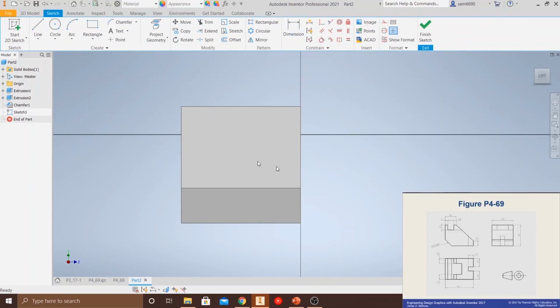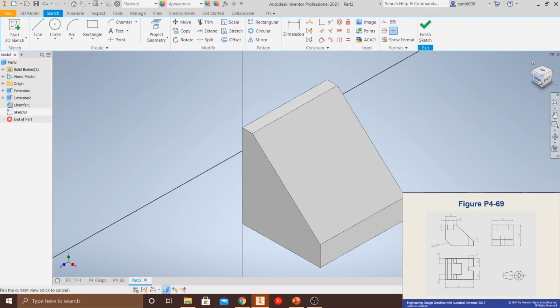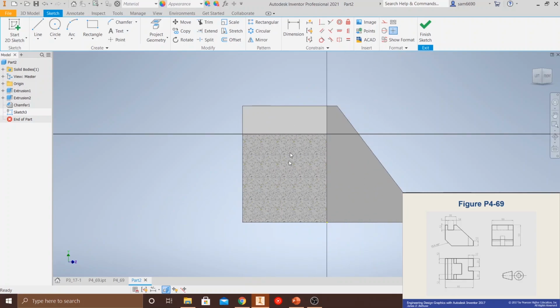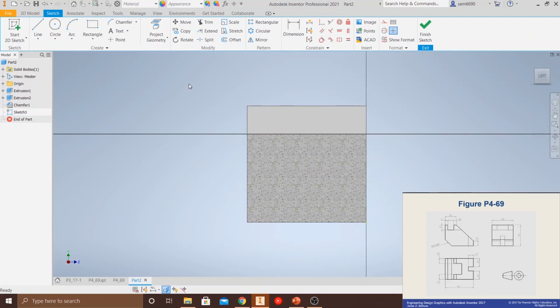Now, you can't see the face. It makes it very difficult. What we're going to do is click FN, F7 if you're working with a laptop, and that'll give you that cut up until that plane that you're working with. Oh, that rotated not the way I wanted it to, but that's fine. Here we go. See? It's cut off right there. So now we can work with this plane in a much easier fashion.